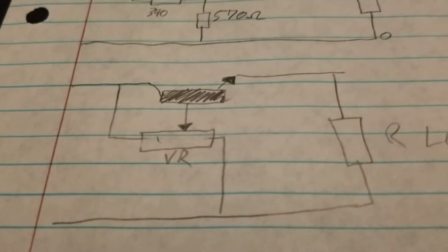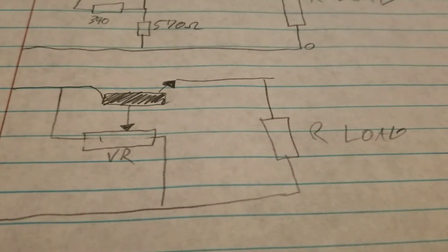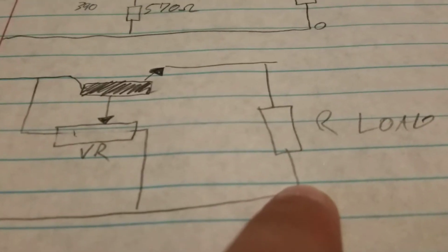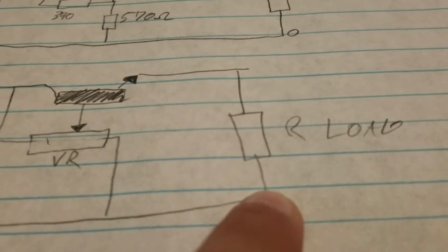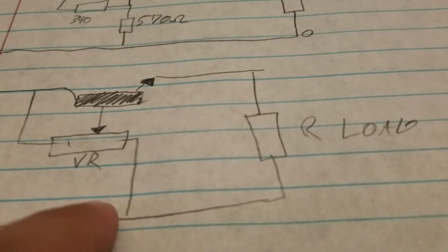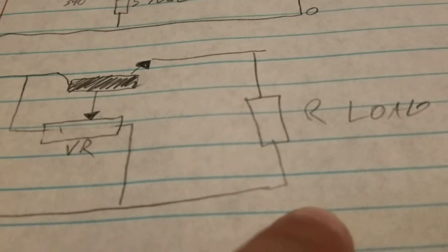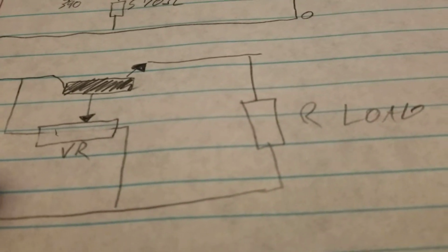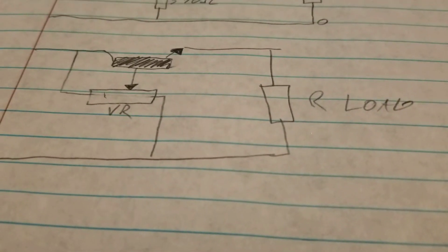And you can even have a little bit of an adjustable supply by using a variable resistor for your load. Because say, like I said earlier, our load's changing by quite a bit for some reason. If the resistance goes up and you need to lower the voltage to keep the voltage constant, well, you can just go in there and tweak the resistor. Let's say the current's gone down again, and so the voltage is starting to creep back up. Well, you can go in there and turn the resistor back up. Now that's kind of annoying. You have to go in there and tweak it.